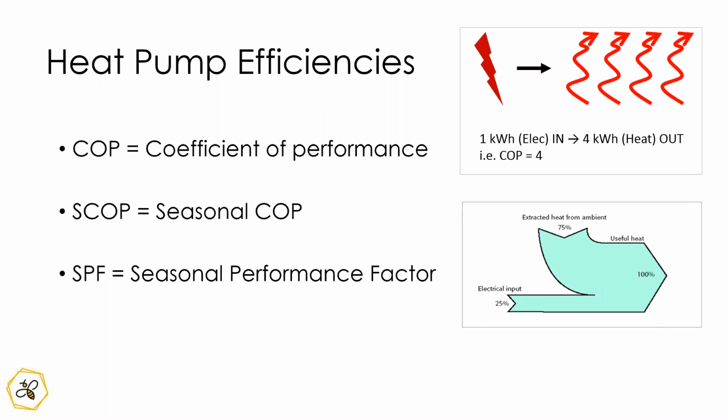And there is a theoretical best COP, and that's defined by the Carnot cycle. I think Tristan touched on this in his presentation, the Carnot cycle, but real heat pumps don't actually match the theory. COPs are at best about half the theoretical one, so that's what we've got to work with. And just a fun fact for you, we've talked about John Cantor and his website and his advice. Cantor happens to be Carnot rearranged, so there you go.